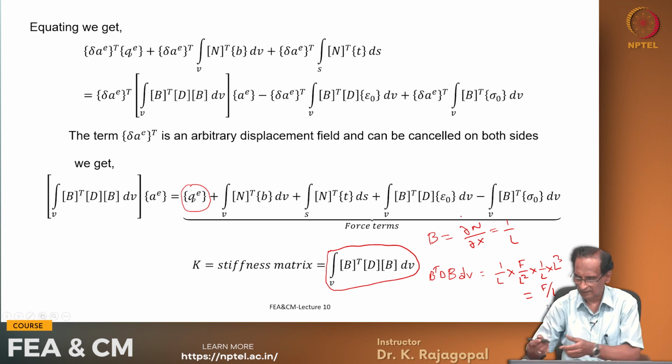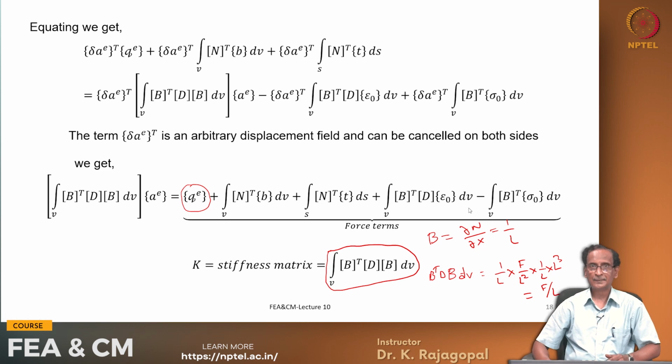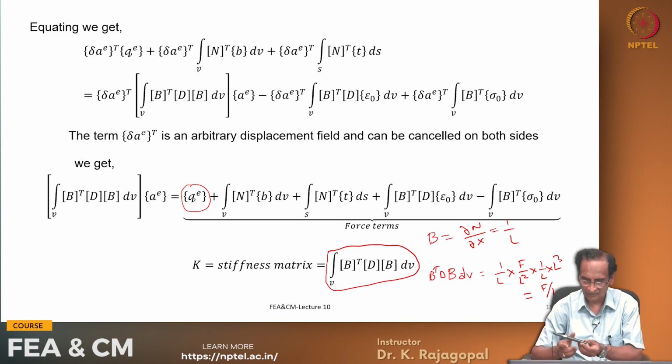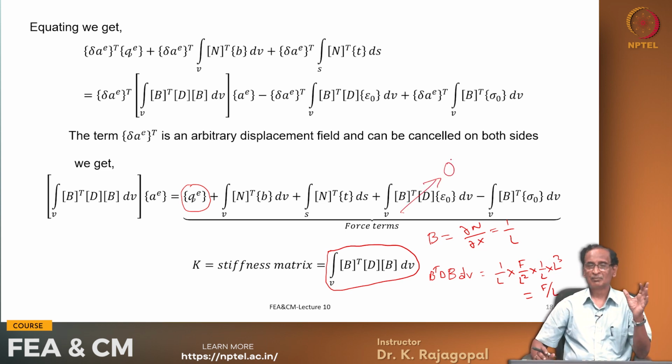What an initial strain is in geotechnical engineering is very difficult to define, because our soil strata may have millions of years of history, and for defining the initial strains we need initial configurations that we do not know. Usually we neglect this and do not consider initial strains, because we are more interested in what happens after we construct, let us say, a building or an embankment or a tunnel.